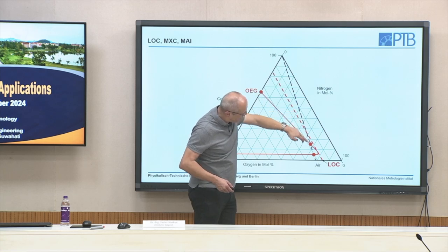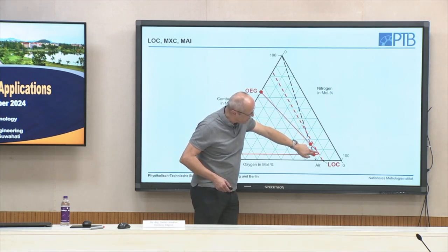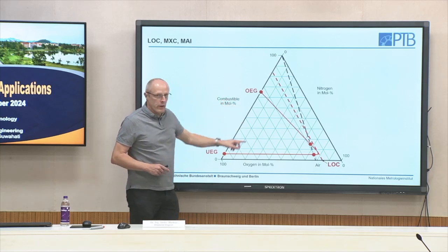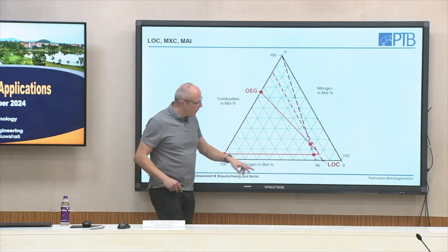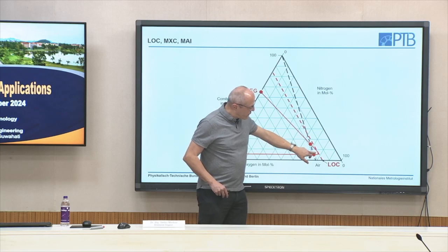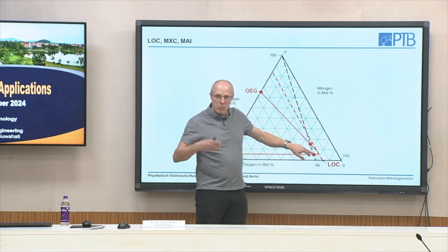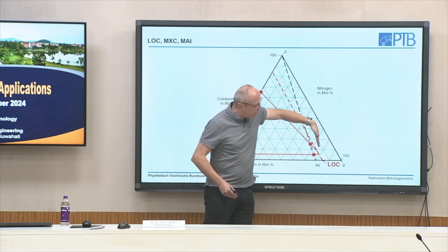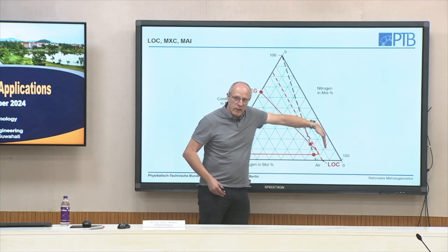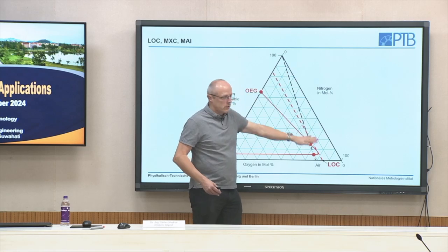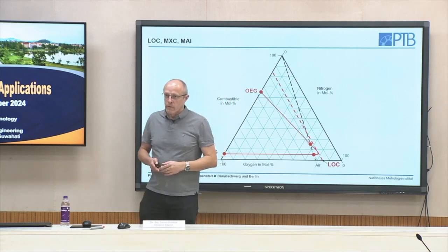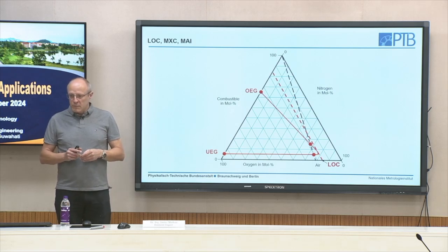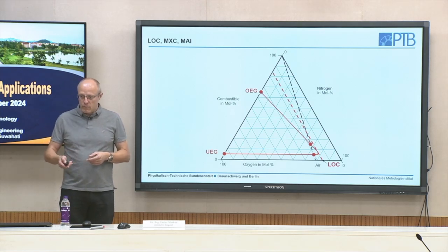So here we hit the explosion range, and the idea is this: when I know this value, I just have to take care that in my lab, in my chemical plant, I always stay on this side. Then I never ever get an explosive mixture. Therefore, if I know this quantity, I can optimize my safety measures with this quantity.